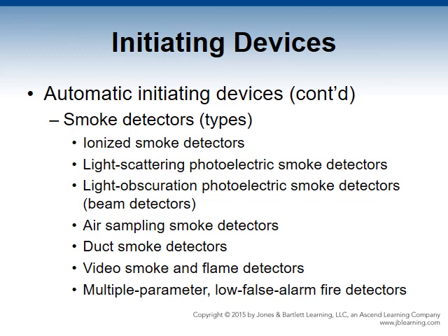Air sampling smoke detectors, also known as aspirating detection, are sophisticated systems designed to draw air from the protected area into the chamber for analysis. The system is capable of detecting unseen byproducts that form in the pre-combustion stage, long before an occupant would notice. Continuous air sampling smoke detection draws air through piping, past filters that remove dust, and into a detector that uses a light source and receptor to measure the reflected light.